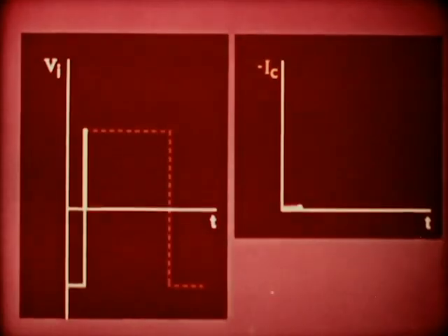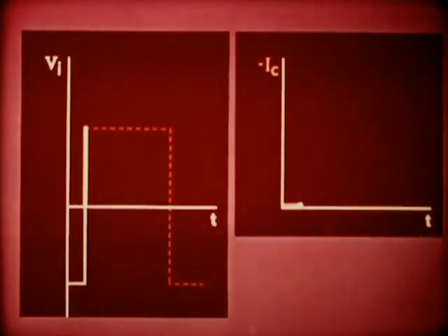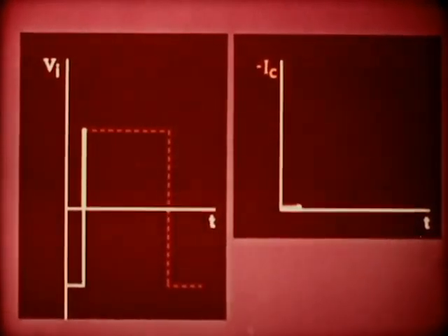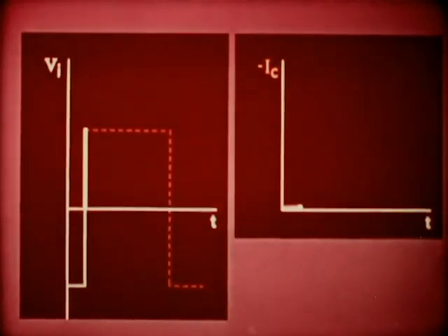Therefore, the electrons in the base and the holes in the emitter, which contribute to the input current, are absorbed in creating a narrower emitter-base barrier region. This continues until such time as the barrier becomes biased in the forward direction, after which the holes start to flow into the base. The time taken for this space charge region to become neutralized is called the turn-on delay time, TD.